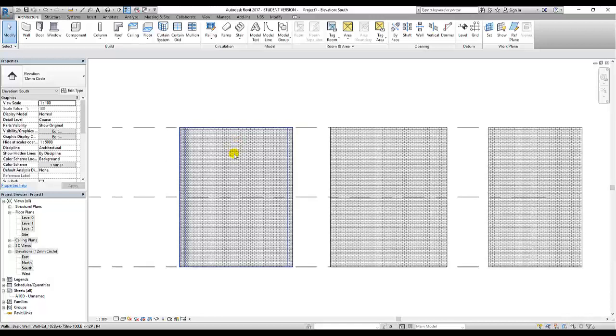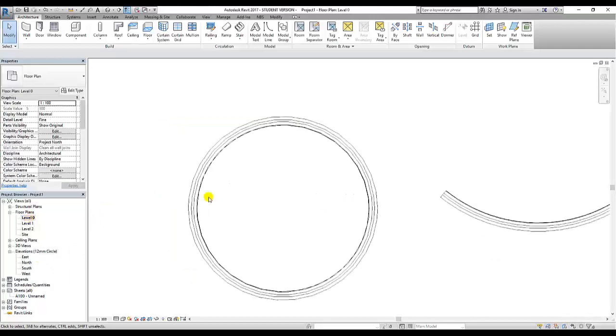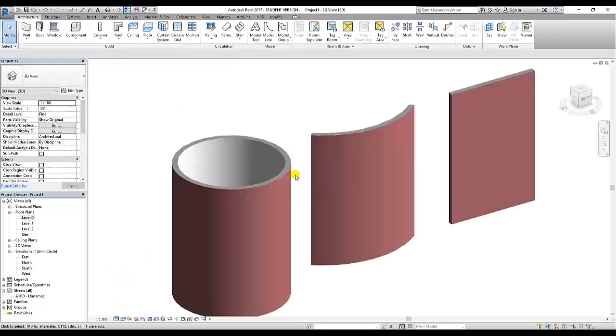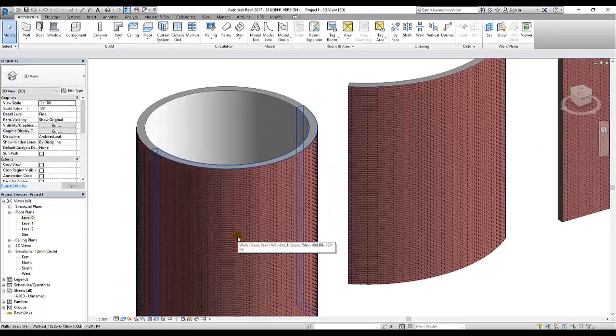So it's all scale related. The drafting type hatch is one of these. If we go into this plan view at 1 to 100, it's that size. If I go into it at 1 to 10, it scrunches up. So that's a significant difference between that type of hatch and the one you see in a 3D view or a 2D view as well.